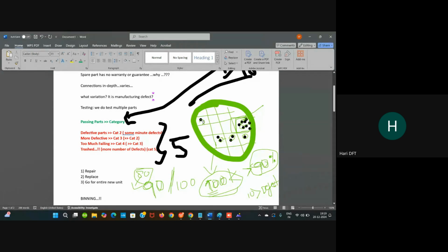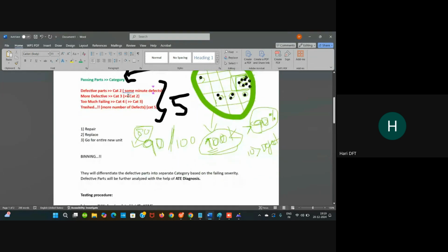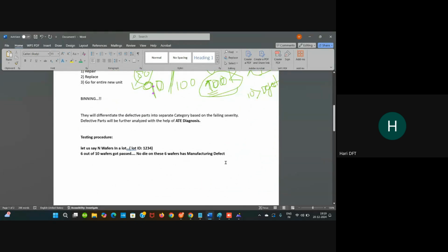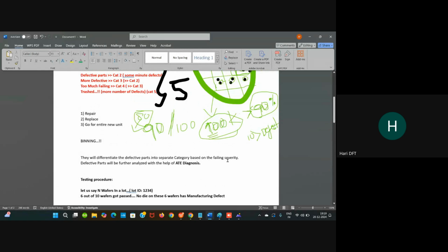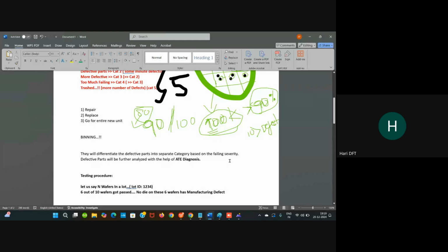Depending upon the yield, when Venkatesh garu asked about the yield, the yield will be calculated per lot. Suppose, consider there is a lot consisting of 10 wafers. For each of the 10 wafers, they will calculate the yield. For the entire lot, they will calculate the cumulative yield of each wafer.